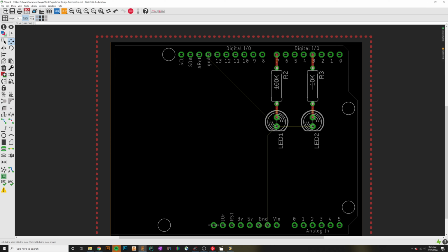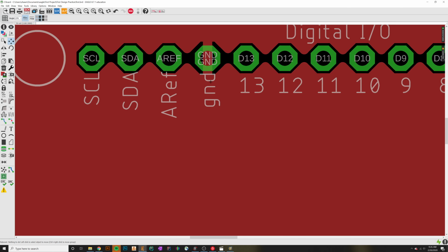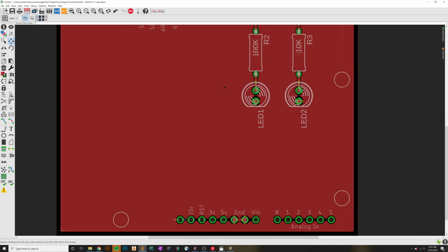I may move it all the way over here, and if the only way I can make that connection is by ground, I will have all of these points that they need to connect back to. If this doesn't make sense, it's going to make sense later. As I hit rat's nest, some of these lines will update. And I think for the most part, lines won't update, except that they will update because I had the ground plane here, so all of those lines have now disappeared.